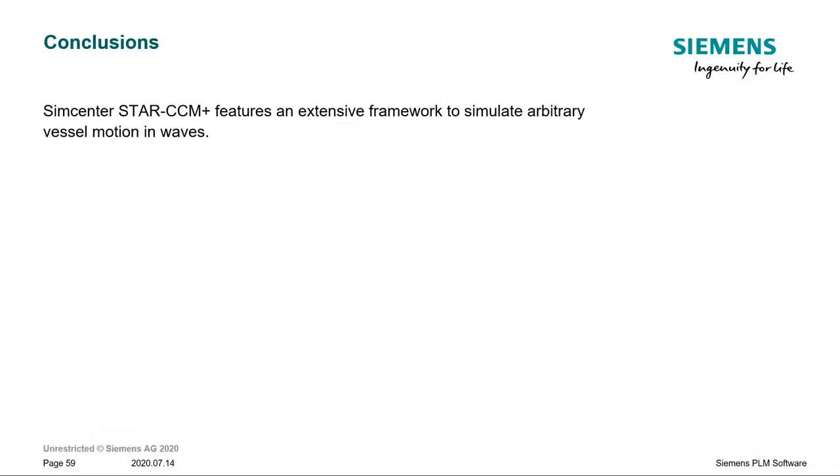Okay, so in conclusion, summarizing, I would say that SimCenter Star System Plus features an extensive framework to simulate arbitrary vessel motion in waves. A very important ingredient in that, which was the basis of almost everything, is the forcing method, which allows to set a narrow domain and, as we have seen, a domain that moves, what I called the moving forced wave tank.